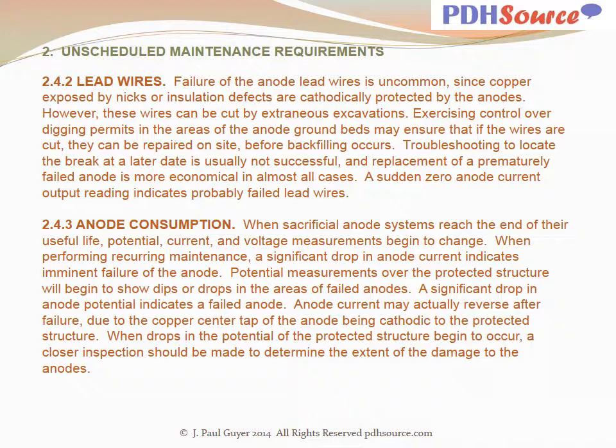Troubleshooting to locate the break at a later date is usually not successful, and replacement of a prematurely failed anode is more economical in almost all cases. A sudden zero anode current reading indicates probably failed lead wires.